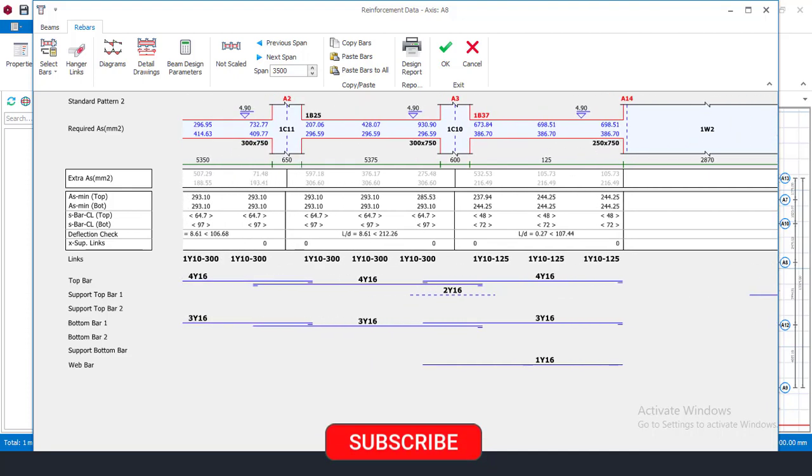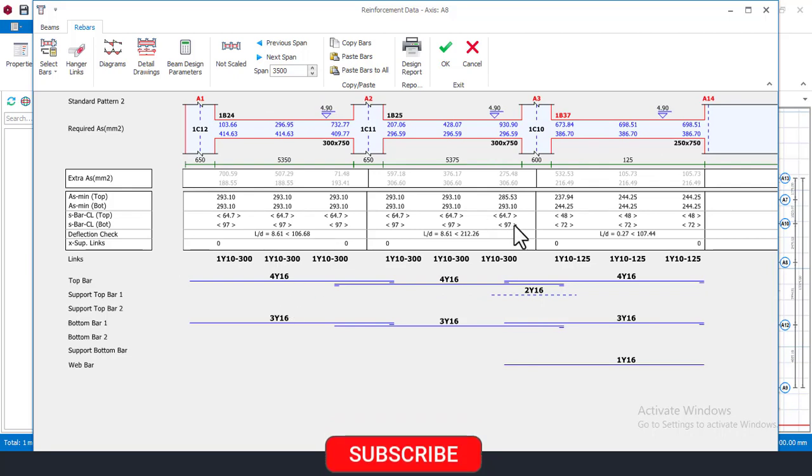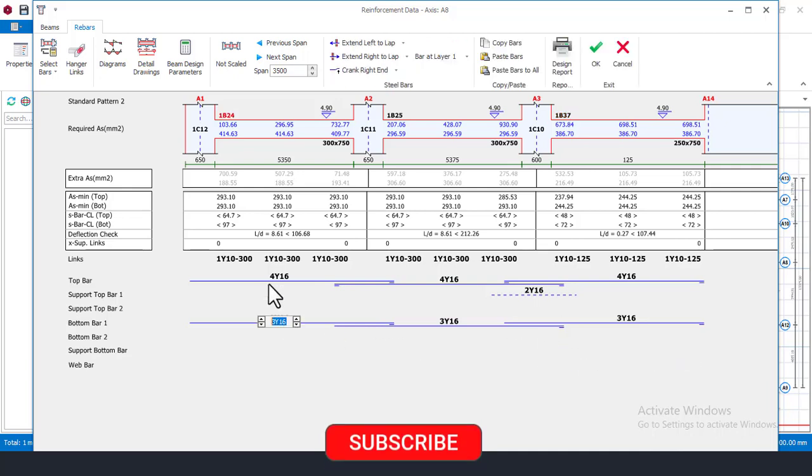Change the bars based on what you think and what you feel is okay. And when you have done that, you check again if everything is okay on that. Okay, and once it's okay, you accept it. Okay. So right now, I don't think this bar here is just a waste of money. So I'll come again right now and check all my bottom layer here if everything is okay, and check my value ratio and everything looks okay here. I can choose to accept this right now as it is, 3Y16 at the bottom.